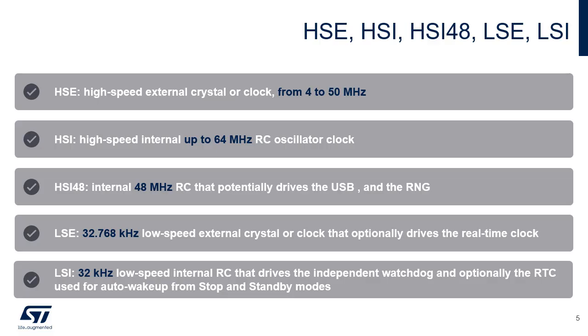The low-speed internal, or LSI, oscillator is the unique clock of the independent watchdog and can be the clock of the RTC. It can be kept running in all stop and standby modes. The clock frequency is 32 kHz.